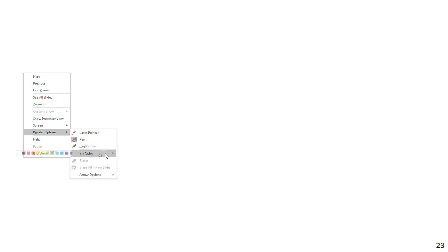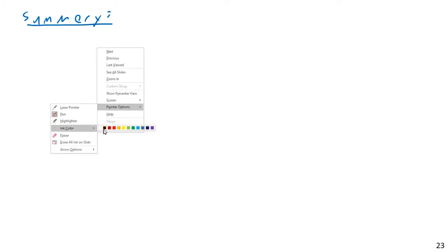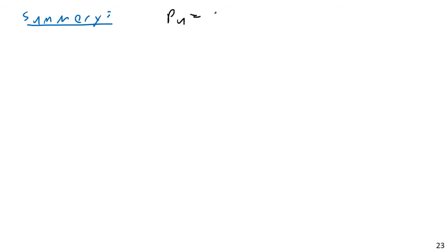So let's do a final slide where we sum things up a bit. Summing up. Maybe I'll do this in blue. That's what I used for my main headers previously. Summary. So here, first, our ultimate loads Pu equals Ru equals 212.2 kips, same for both our connecting element and our tension member. And for tension member yield,